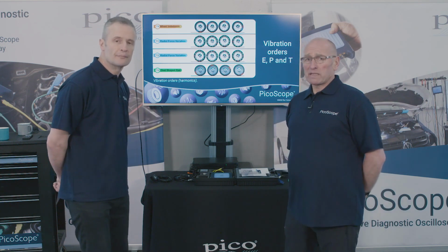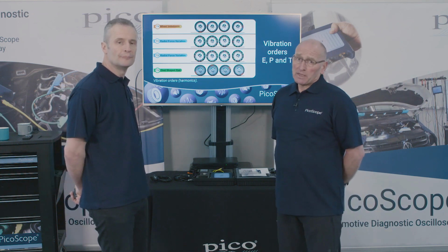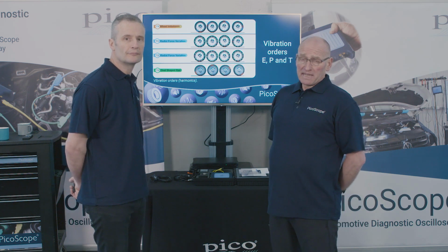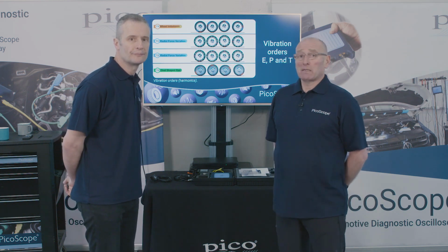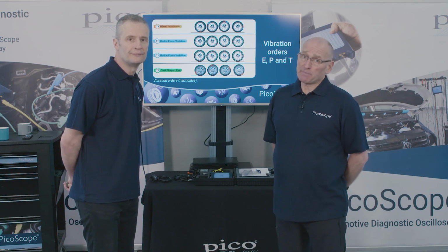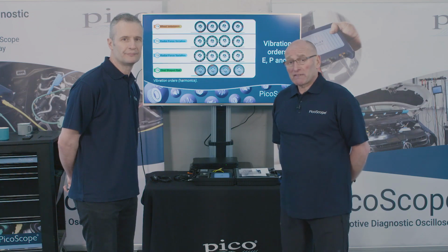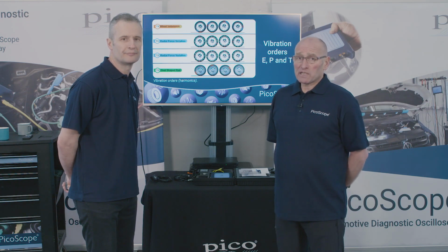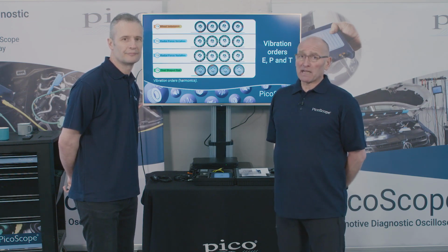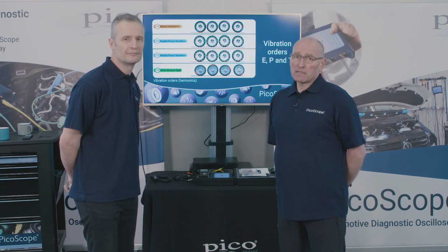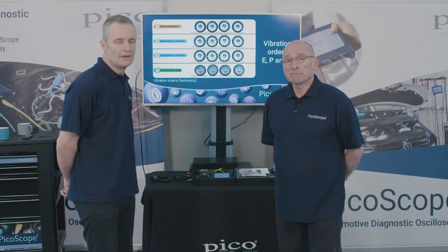Also be aware of the fact that when a vehicle is new, the manufacturer will identify a high spot on the rim, and the tyre manufacturer identifies a high spot on the tyre. These, when correctly fitted, are normally set 180 degrees apart to minimise out of balance forces. Regrettably, when the vehicle ages, we no longer have that ability. So quite often, a second-hand vehicle with older rims and older tyres does suffer from this vibration issue because of incorrectly paired components, basically. Absolutely right.